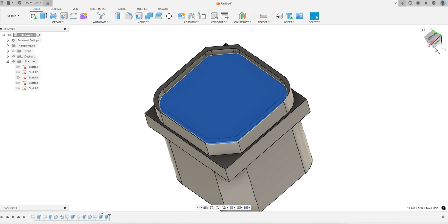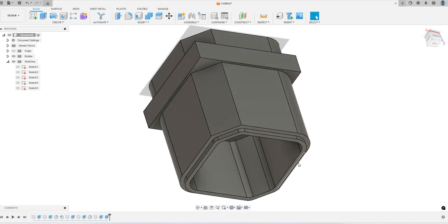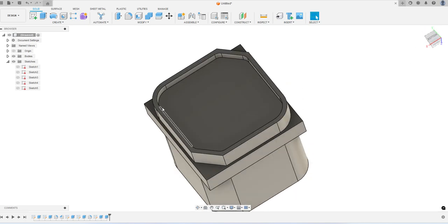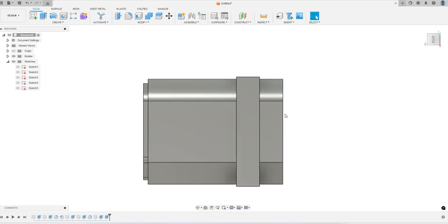Really, the only place that needs to be that deep is the interaction between this portion right here and that lip right here. If you wanted to have a gap and then come up in the middle, that'd be fine too. We do really want to have that 0.3 space between that edge inside of there, like the top part of it, and the clamping boss, which is this area right here. This is 1/2 of an inch because this was 2 inches. This is 1/2 of an inch, and the whole total is 3. That is a requirement. I need 1/2 of an inch.